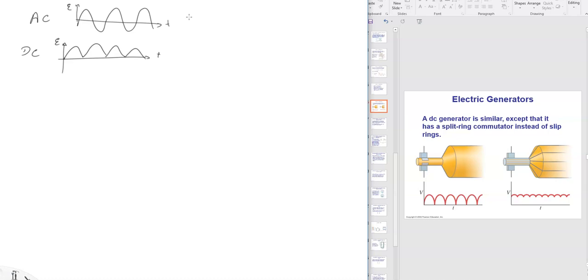AC has some other advantages. AC is easy to convert. If you want to change the voltage, let's say the generator produces something like 170 volts, but for your household appliance, you need only 12 volts. We say the average is 110 volts, okay, the average, and you want an average of 12 volts. These kinds of transformations are much easier when the voltage goes back and forth.